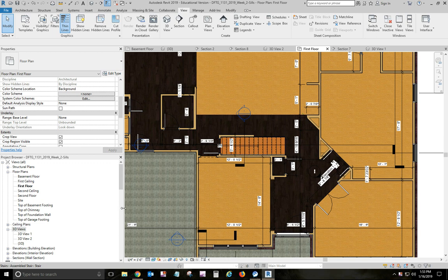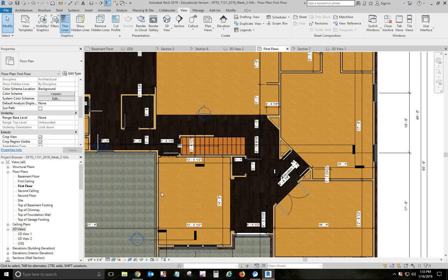Now we're going to do stairs. I got the stairs for the basement done, figured out. I do want you to go ahead and add hardwood flooring in this area because that's going to affect our stairs. The drawings on sheet A7, the stair sections, do not take into account any finished flooring. His dimensions there go from subfloor to subfloor, and we want to take into account finished floor. So go ahead and add hardwood flooring on level 1.